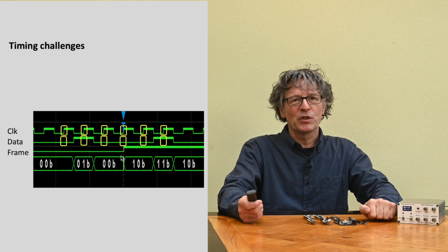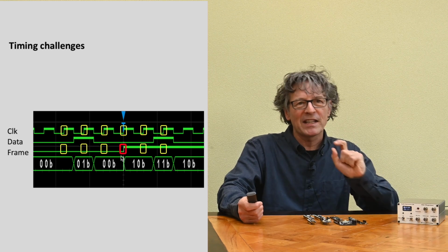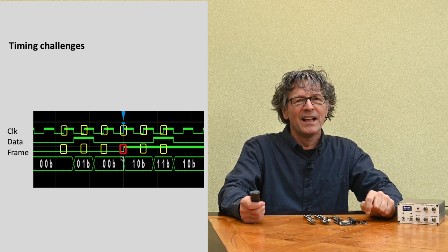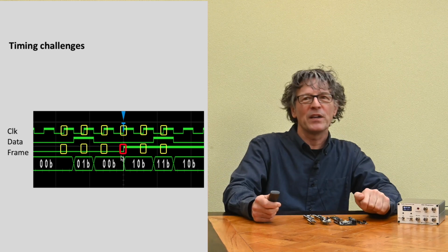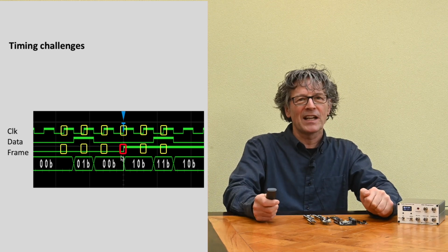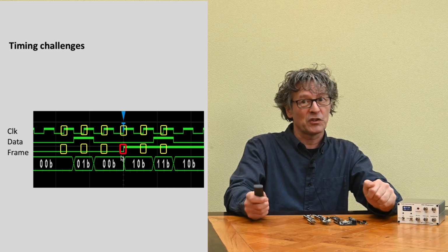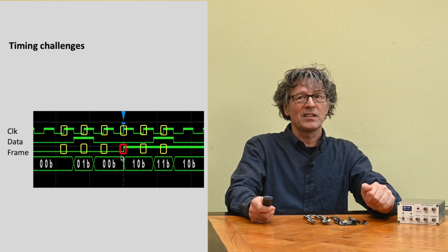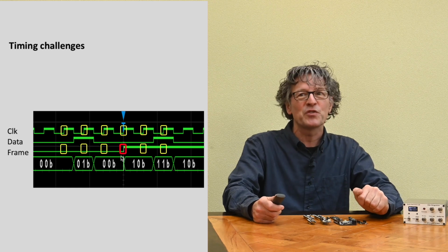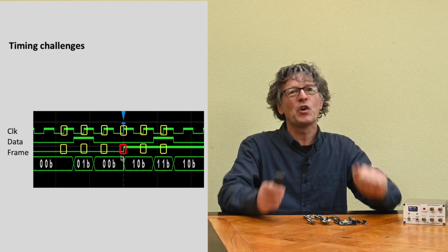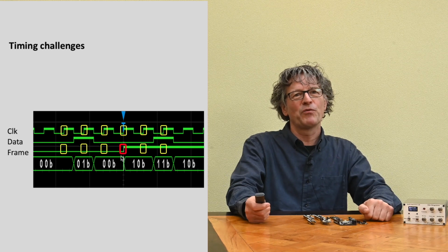However, if I want to capture the frame rate, what we do see here is that the frame signal goes positive at exactly the same time as the clock signal. And sometimes the one signal arrives first and sometimes the other signal arrives first. So when I was analyzing this signal, sometimes I get a sequence of 511 bits, that's correct. Sometimes I would get a sequence of 510 bits, and other times a sequence of 512 bits, just because they happen to go up exactly at the same time. This is not necessarily a fault of the SMIQ.